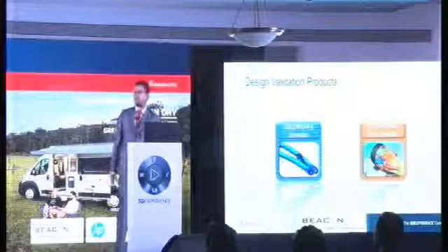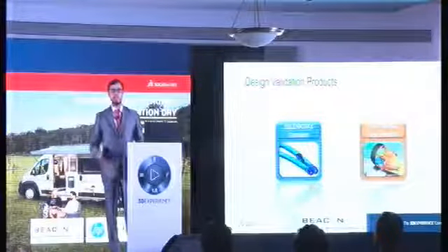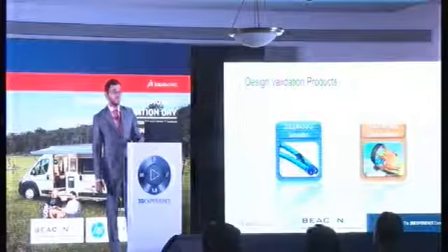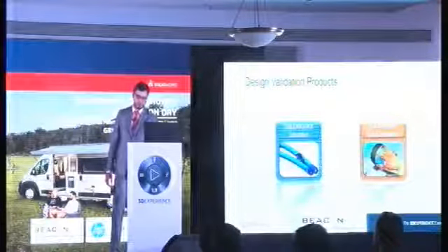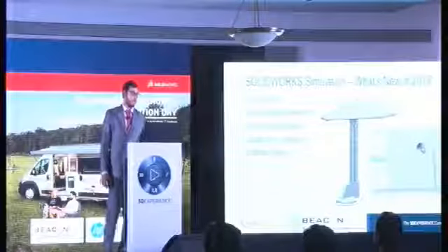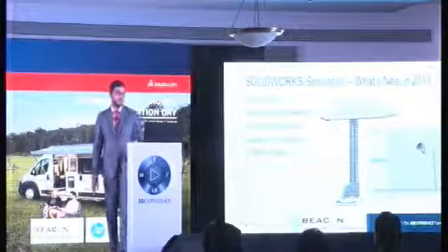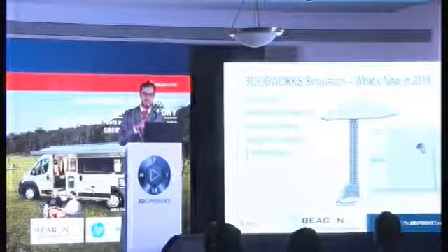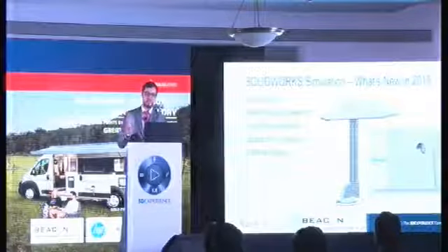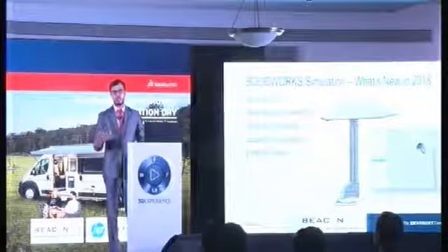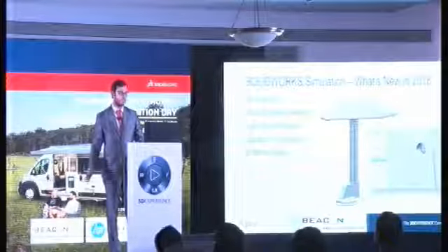So in this session I'll take you through all the new features which have been involved in SolidWorks simulation and flow simulation. So starting with the SolidWorks simulation, first of all, we have topology study, we have stress similarity detection, we can import directly the study features from the parts, we have updated pin connectors and email notification. So let us have a look one by one what these features mean.